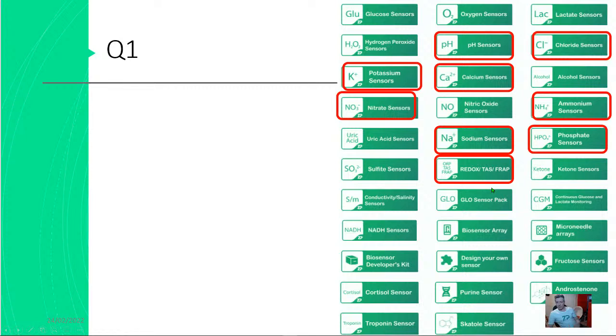Oxygen's a bit different. It just occurred to me last night about the oxygen. So I've highlighted oxygen a bit different. I think this is kind of interesting to some of us that are a bit more geeky on this stuff, that you could measure oxygen using essentially a redox probe, a reduction oxidation probe. Now a redox probe, all it is actually a platinum electrode. And you can also measure oxygen in an amperometric mode. So at ZP, we tend to actually measure oxygen in the amperometric mode.